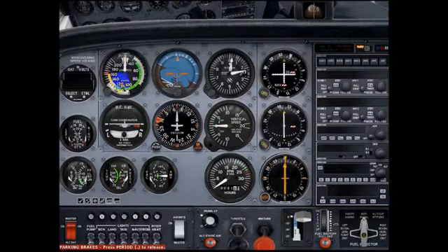The pitot, if you covered the ground school, and that's why I highly encourage you to look at the private pilot series. The pitot tube feeds this instrument. All right. And as well, the static port feeds it as well. So the pitot tube takes in ram air pressure, and balances it with static air pressure.